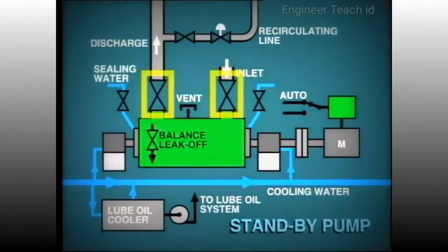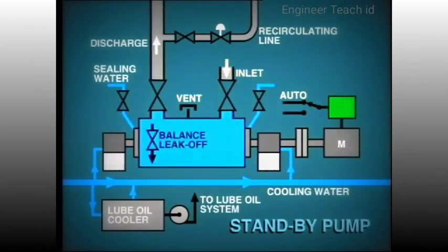Make sure that you're familiar with all the mechanical details of your particular feedwater pumps, and especially the procedures for making the pump available. For example, on the standby pump, you will typically need to make sure that the inlet and outlet isolating valves are open, the pump is fully charged with water, and all air has been vented. The recirculating line isolating valves are open. The recirculating line control valves should be open, as there is no flow passing through this standby pump.